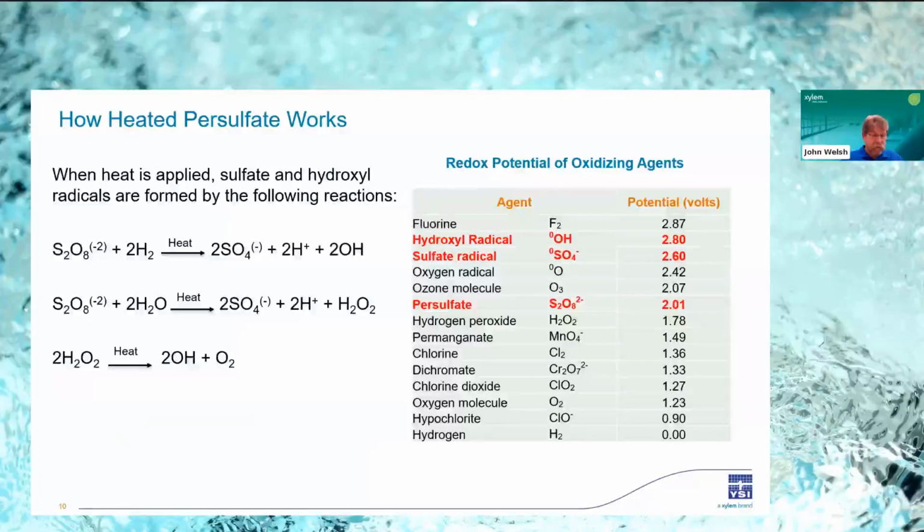The persulfate reaction is based on a wet chemical oxidation using sodium or ammonium peroxodisulfate, also simply referred to as persulfate, and orthophosphoric acid as reagents to convert any compound containing carbon, including organic carbon, to dissolved CO2 within a reactor at 98 degrees C. The 9220 uses sodium persulfate and phosphoric acid.